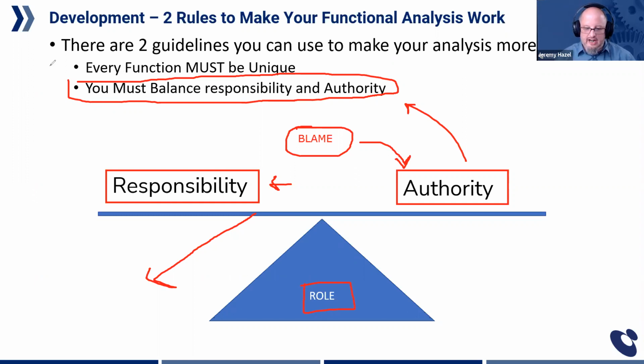And the second rule that I do: every function must be unique. I was fortunate enough to work with a company that made half shafts not too long ago. When I looked at their DFMEA, every function was to transmit torque. It didn't matter what level of design, it didn't matter where. If you have a duplicate function, and there are very few exceptions, you have done a poor job. It's a lazy FMEA, both D or P.